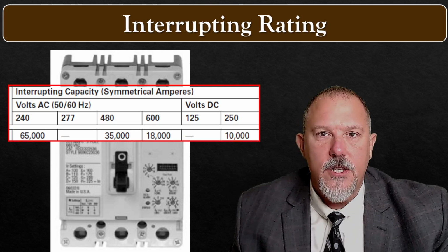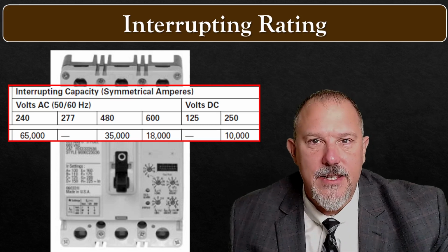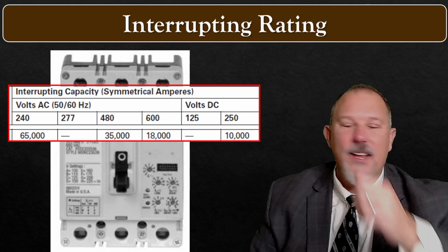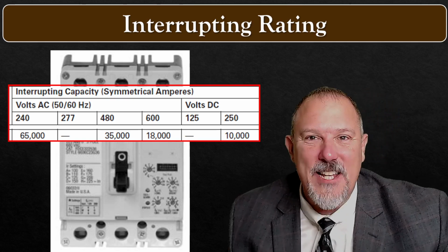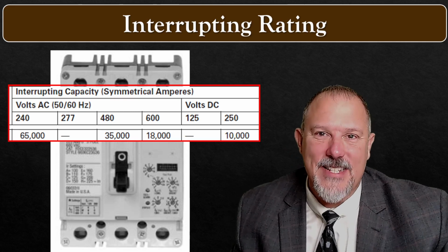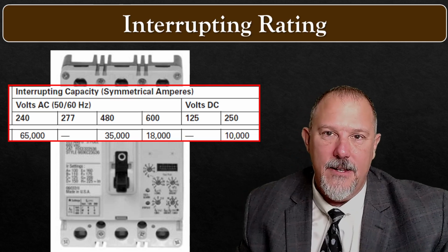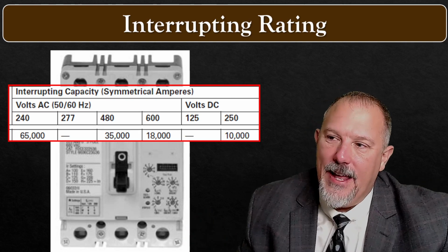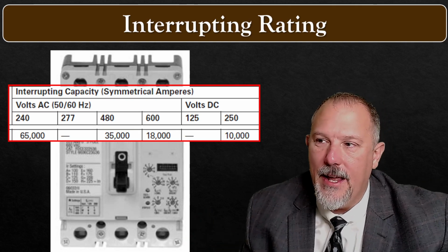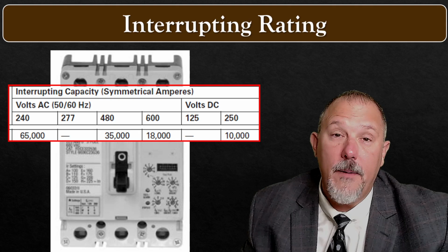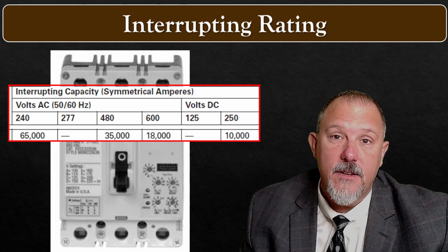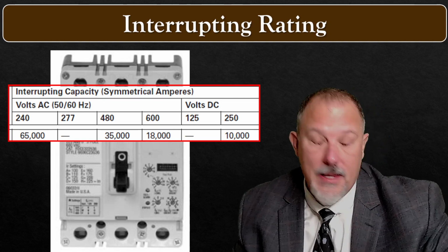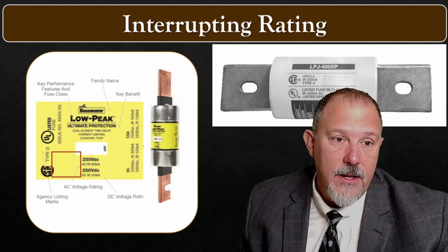And he goes, Tom, he's using it at 480 volts. I'm like, oh, well, then he doesn't have a 65,000 amp interrupting rating. He says, I've been trying to tell this guy that. Then I called the contractor back and explained it, and he said, oh, fundamental mistake. He just missed it. Bad day, but that's okay. We all have those days.